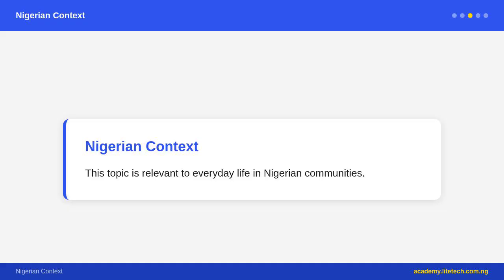Walls, can be structural, load-bearing walls carry load, or non-structural, partition walls just divide space. Slabs, floors and roofs, flat horizontal plate structures that carry the live load and transfer it to beams or walls. Frame structure, a skeleton of columns and beams, steel or reinforced concrete, it carries all loads. Very common for multi-story buildings. Load-bearing wall structure, walls carry the loads directly. More common for smaller, low-rise buildings.